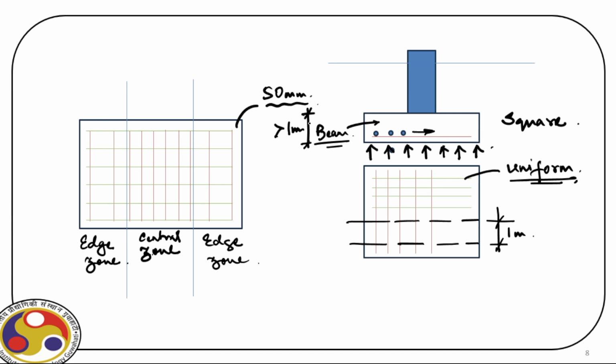But the point to be noted, it does not supersede the requirement based on the effective depth, because the moment you set this thickness D, from there you can calculate the effective depth, and from that you have a minimum requirement of steel for this beam design. So if that minimum requirement is more than this 360 millimeter square, then you have to provide that accordingly, right? So that actually covers the steps for foundation design. So now let us just consider an example.